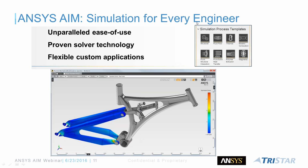Here you see a quick snapshot of the process templates. When you launch ANSYS AIM, that's what you get. You pretty much start with a template, and the template guides you through the workflow, the process and the steps. First you import geometry, then edit the geometry, create the mesh, set boundary conditions, solve the physics, and then view the results. It guides you through that depending on the template you pick.